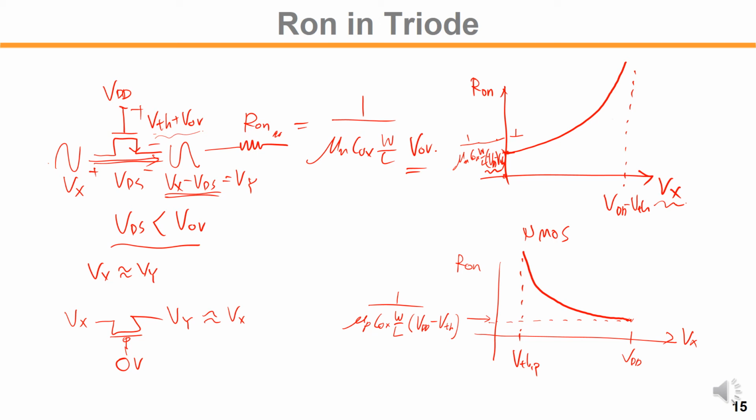So as you can see, the resistance of the NMOS and PMOS are not totally linear over the bias voltage. The operating voltage on the source and drain actually determines the actual on resistance. So having a single transistor as an analog resistor is not a good idea, because we see a very nonlinear resistance out of the transistor.